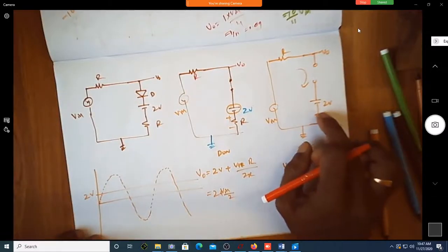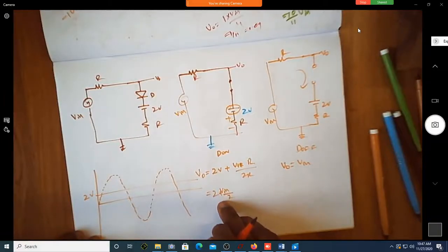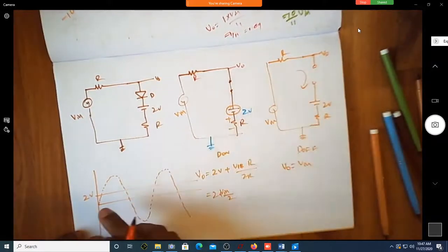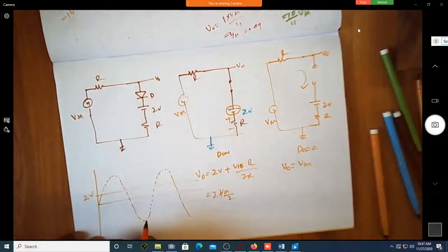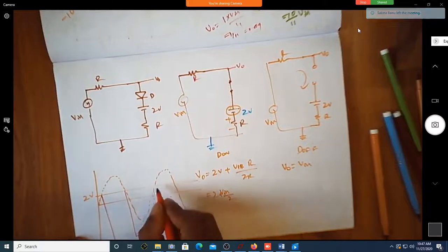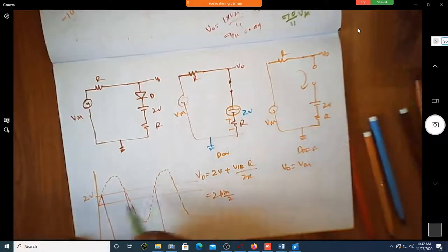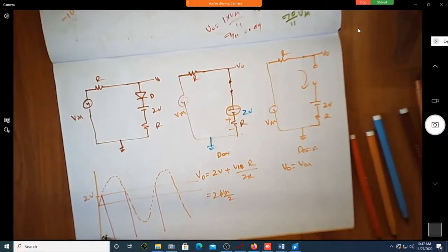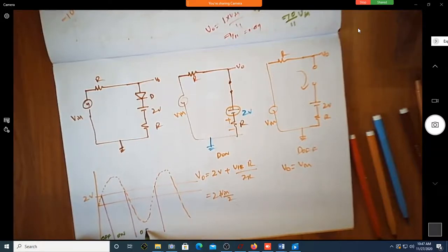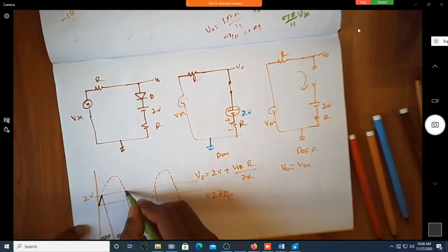One half of it is here, the other half will be here, the other half of your input voltage. So this is V in by 2. Where does the other V in by 2 go? It will be over here, as the drop. So anything more than 2 volt, the diode is on there. Shall I write these as the transition points? Here it is off, this is on, then off, and on. When it is off, it follows the input perfectly.